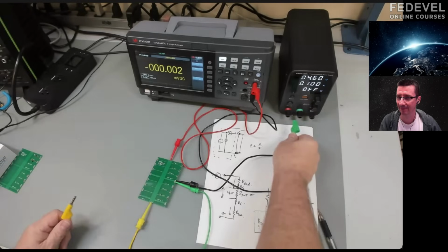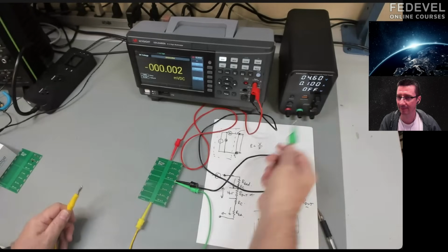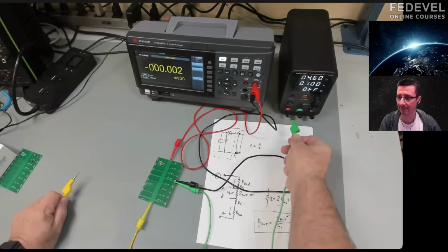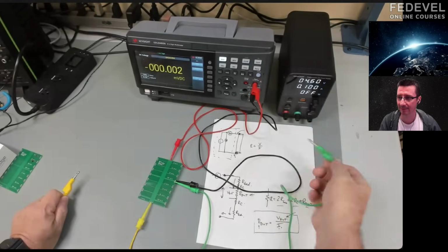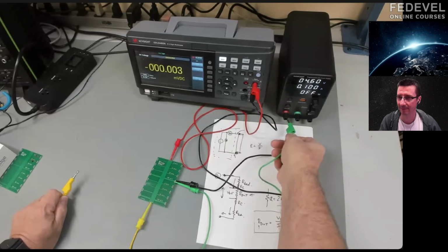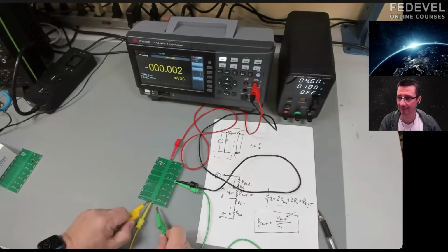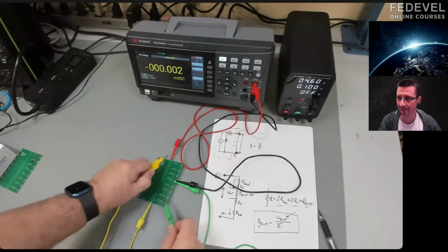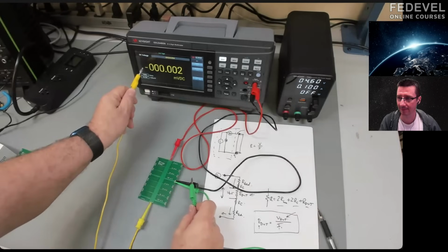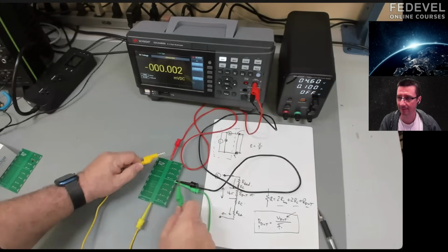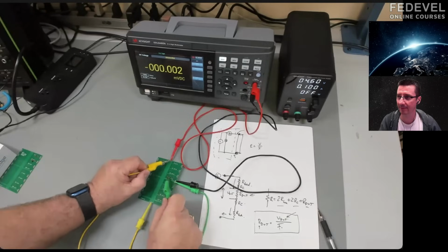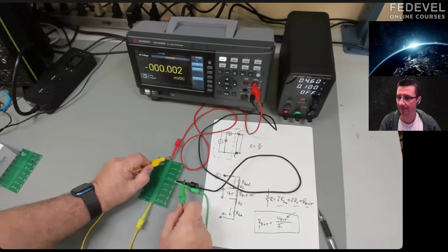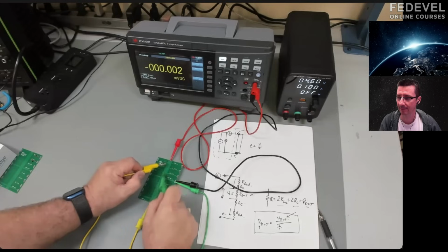So I have a power supply here. This is a constant current, constant voltage power supply. We're going to set a current in it. We're going to start with 100 milliamps, and so we're going to send a current through here, and it's going to go from the bottom. The voltmeter, the digital multimeter set as a voltmeter, has really high impedance. In fact, here it says 10 megaohms. So there's 10 megaohms going here, so that's effectively zero compared to the milliohm of resistance.